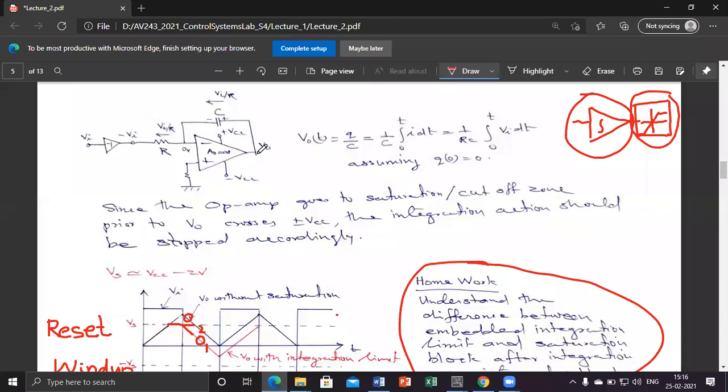Block level only. Probably there is an output stage for the op-amp. You might have seen stages like this. The output stage, I think, is a common collector. Different types of configurations will be there. To reduce the output impedance very small, as you told, a common collector configuration in push-pull mode may be used.